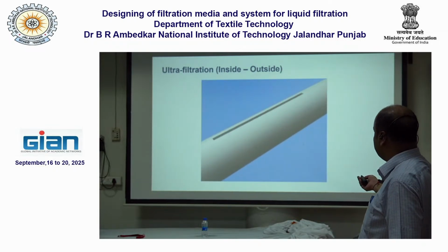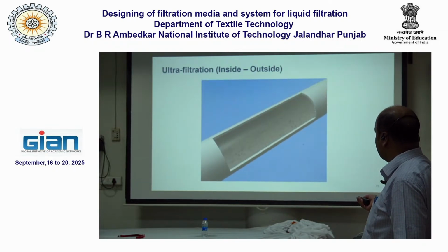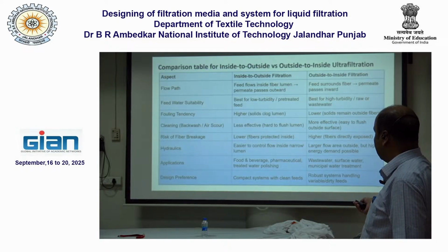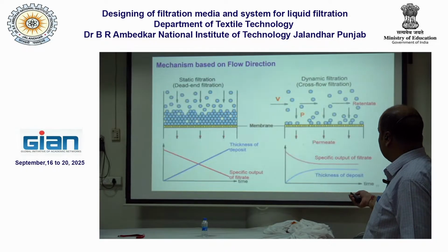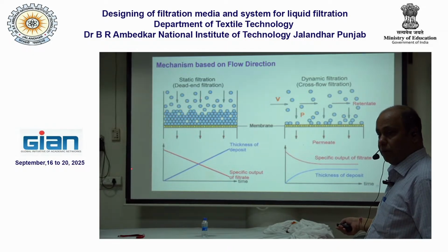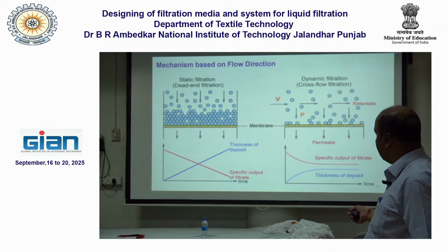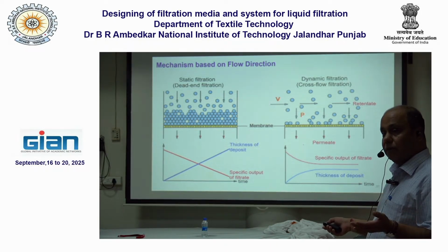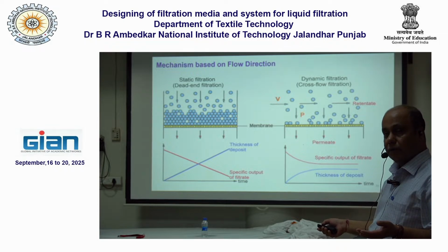Now here you can see this is the inside to outside. So this one is, in fact, the back washing. I am not going into that, but mainly, if you see from here, this is the situation of dead end filtration, because the fluid is flowing across the plane of the media. In many cases we use dead end filtration. For example, cake filtration is possible through dead end filtration only.